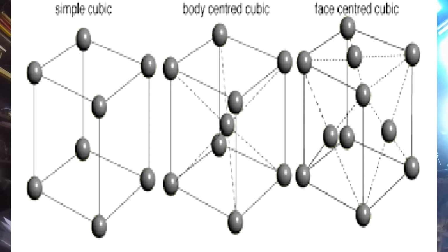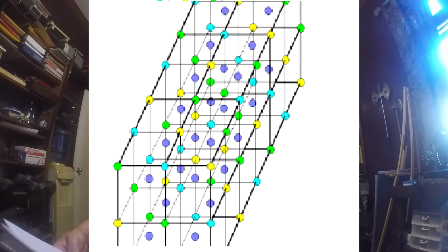As it gets cooler and cooler, the atoms start lining up into the cubic forms, and you will see something like this if you're able to look that closely. The atoms line up and start forming a long line, more uniform than not, and eventually the center stem of a dendrite will be formed.